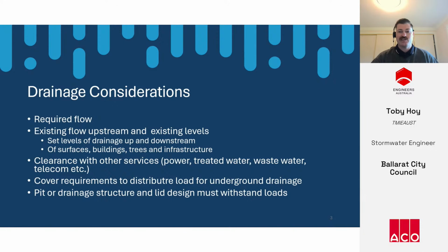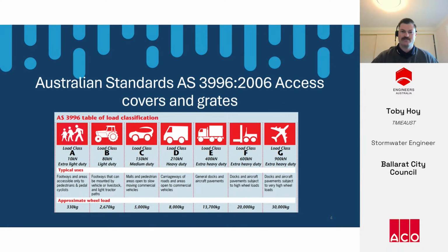Drainage infrastructure, especially under vehicle loads, has cover requirements, so you have to select a material that suits and has the strength to withstand the loads. For pipes, this is often a choice between concrete and HDPE, high density polyethylene, as these are the two most common pipe materials. We can also consider newer or innovative materials such as recycled plastic pipes. When lack of cover over pipes, flow volume or required loading becomes an issue, reinforced concrete box culverts or crown units become the standard product for use.